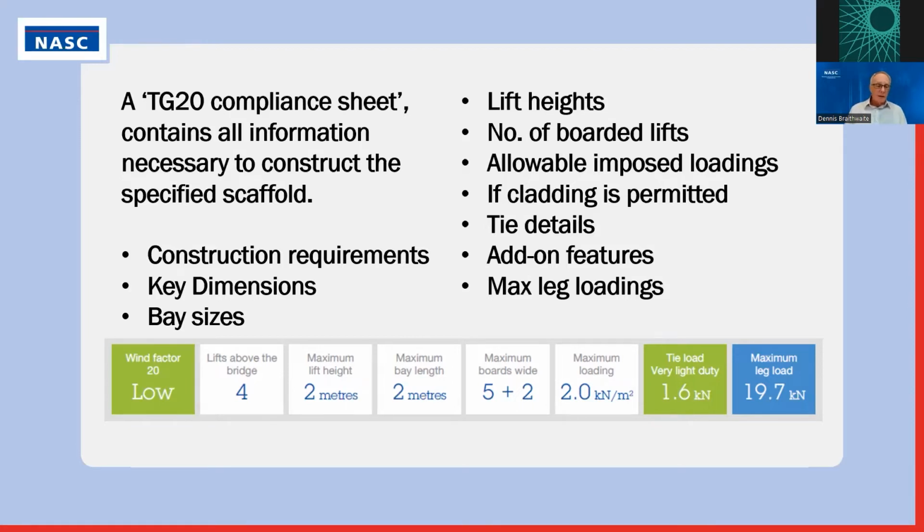It tells him basically the tie load. So, if we're tying to a building or structure, what extra load is the scaffold going to put onto it? And it shows you the maximum leg load for the foundations, so that we can ensure that they're obviously adequate.